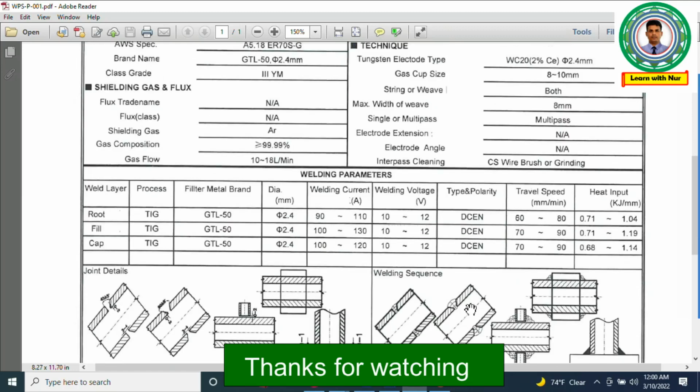Then welding parameters. What welding parameters we have to follow is very important. So weld layer: root, fill and cap, these are the passes for the TIG welding process. Then filler metal brand, and diameter, this diameter we have to use for the WPS. Then welding current, we have to follow during root pass 90 to 110, filling 100 to 130, and cap is 100 to 120.